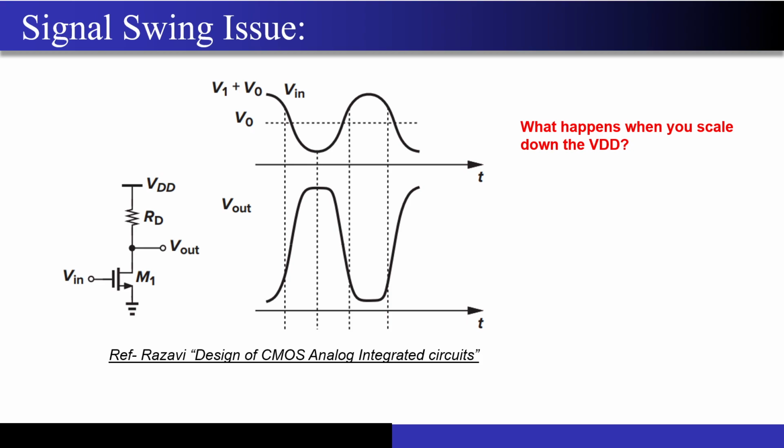Physically, the 2 nanometer channel length is just a marketing gimmick. If you actually try to measure the length, it won't be 2 nanometer. It will be definitely higher, something like 8 or 9 nanometer. They have just given the name of that 2 nanometer technology. But I guess this was not your question, right? You're asking something else.